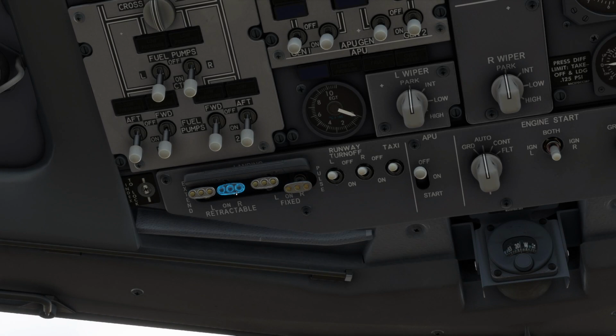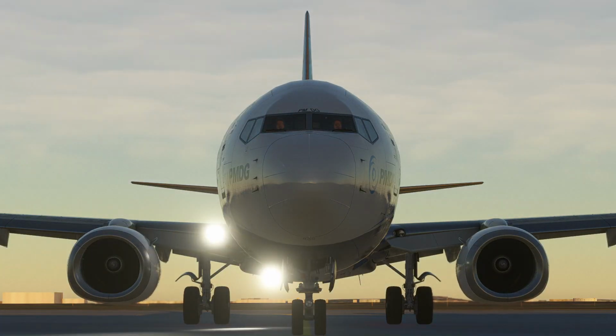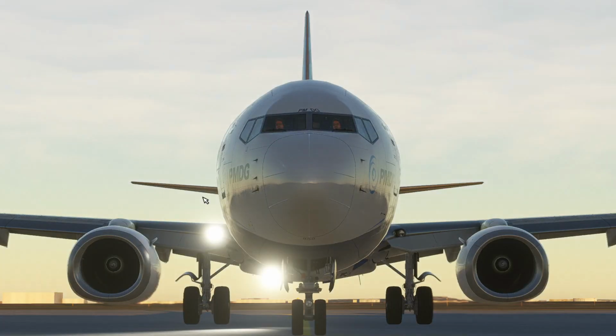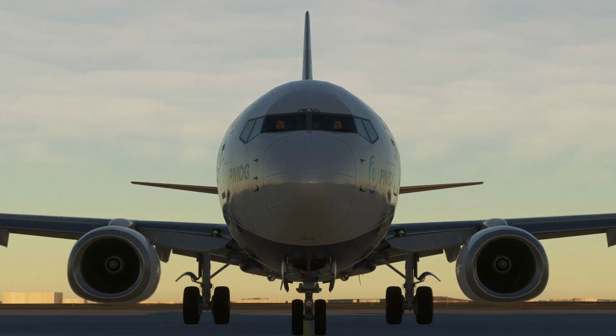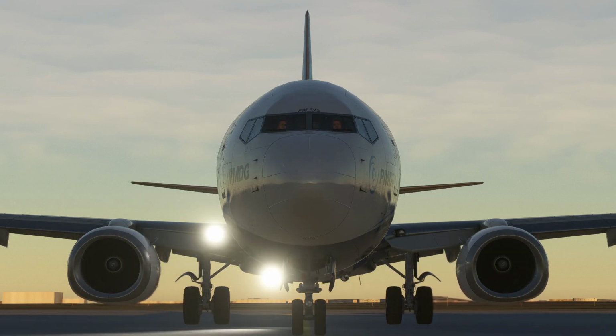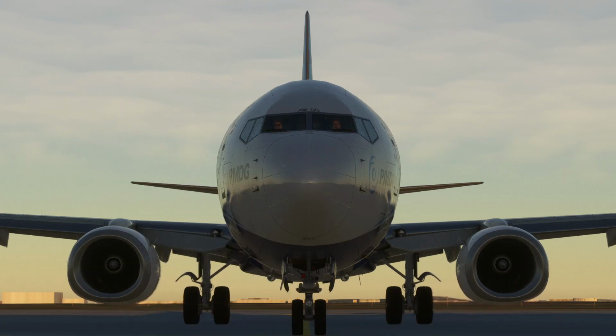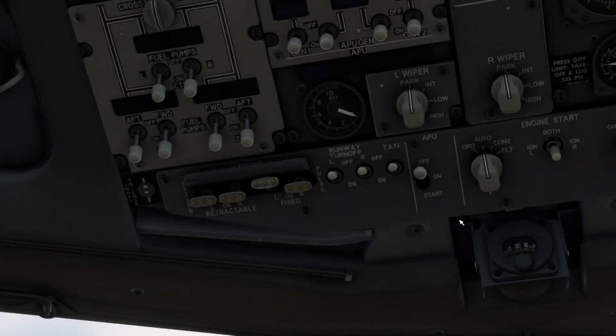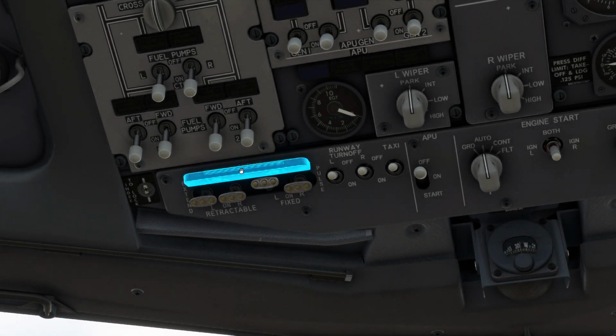But once again the pulse mode for any of these, if it's on, controls the retractable landing lights as well. So in this case you will have the retractable landing lights there. Okay, so in this case you are going to see that the right side pulses and the left side does not. Okay, the only thing you cannot control is only pulse for the retractable one, because the pulse switch once again is attached to the fixed landing light.